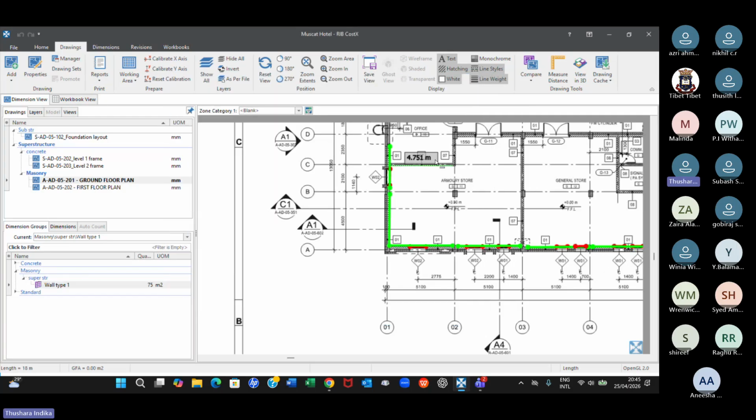If you have separate walls with separate heights, then you need to define heights separately. In this case, I have taken 3.4 as the default height. Using the default height, I have measured the linear meter length, and then you get the area here, and then deducted the negative dimensions, the window openings. We have defined the openings.